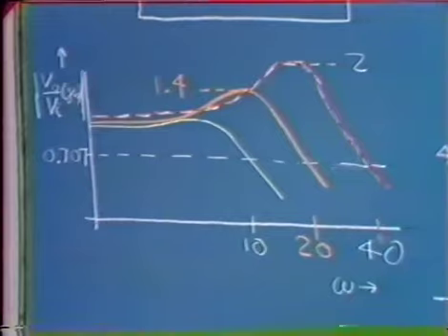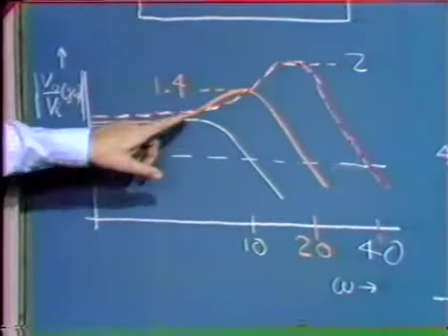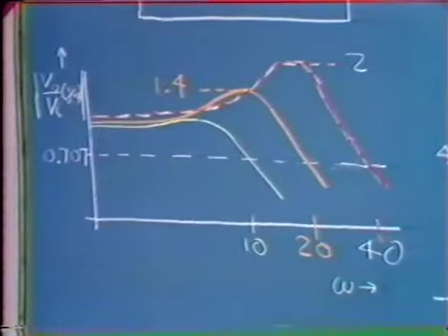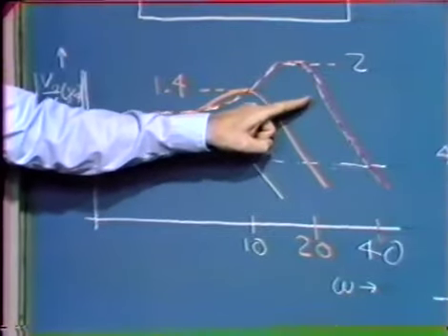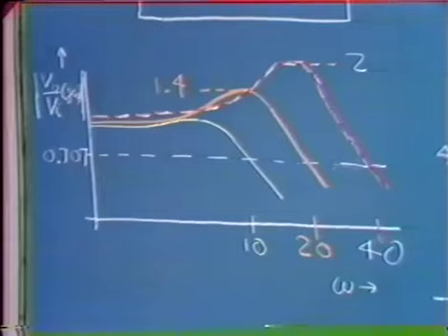So we can quite quickly, with the aid of the Nichols chart, determine the closed loop transfer function of the system, and of course get a very graphic indication of the deteriorating stability as we go to larger and larger values for A0.